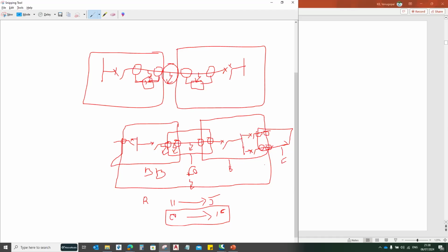So it is very important to ensure that all the protections are overlapped if you are going with more than 33 kV voltages, because it is an interconnected system. But 11 kV switchgear and 415 volts are self-user equipment. If there is any problem with that 11 kV switchgear or 415 volts, the problem is limited to the user. It will not impact other users.